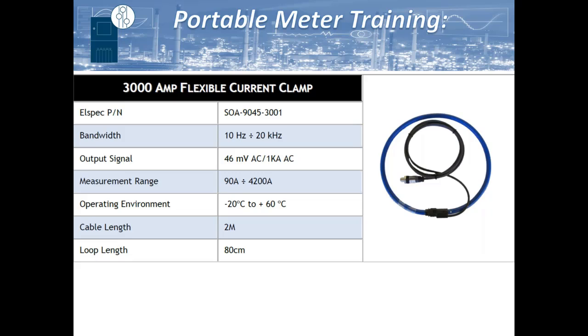So this is good up to 1,000 volts. So you don't want to go in and put this around, 3.3 or something setting. So you want to keep the voltage and the current range about the same. The 4500 is set up to auto detect most of the probes that come with it, so you don't have to worry too much about your settings. Next screen, please.